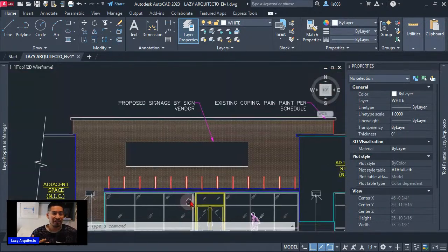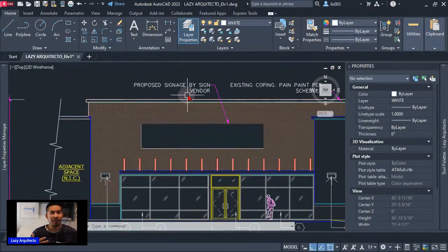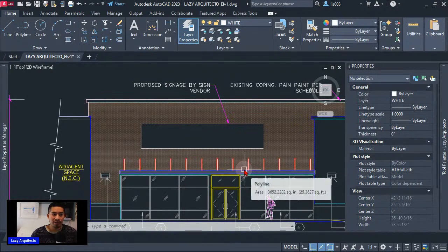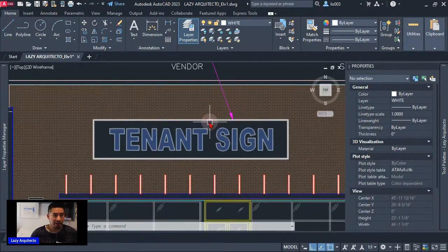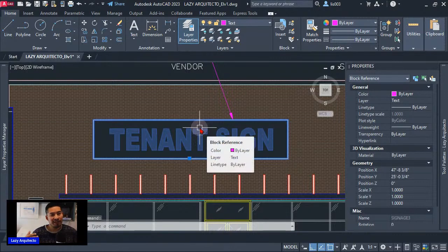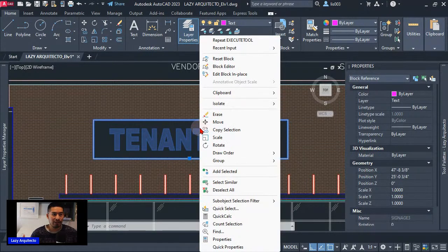So that's a very common problem, especially if you have other drawings and you try to copy and then paste blocks that contain a wipeout inside another drawing. So let me open this block to kind of explain why this is happening and how we can prevent or fix it, right? So let's open this block again with right click and picking block editor.